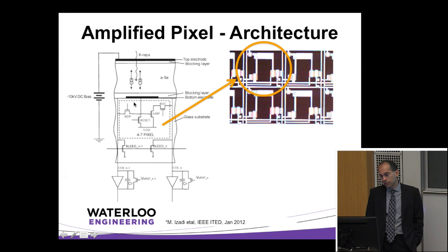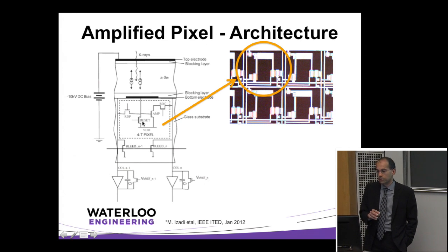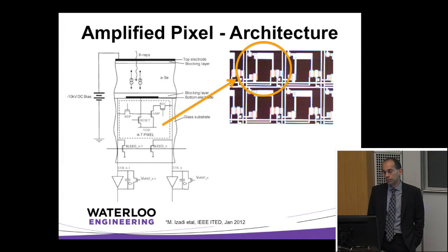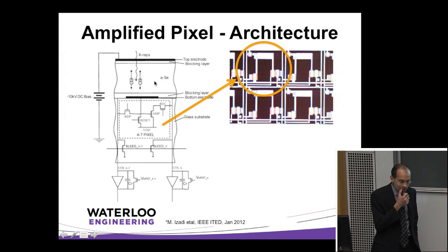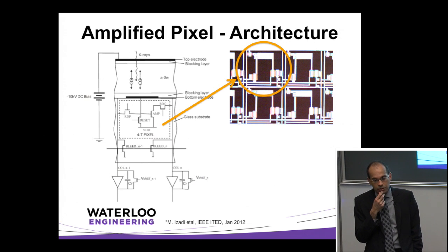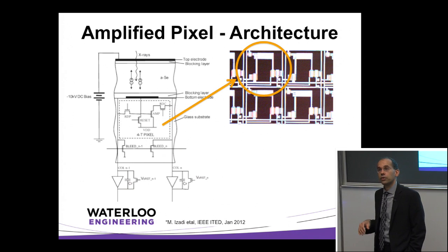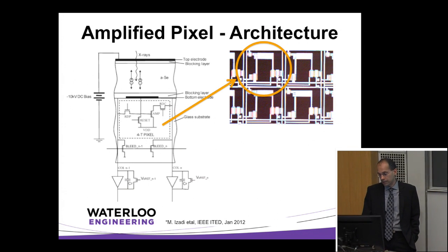So here's another active pixel sensor design. This one's actually a 4-transistor active pixel sensor, not the 3-transistor. We added some additional functionality to increase the dynamic range by putting in the 4th transistor. And we worked with a company based out of Montreal in Canada. They were eventually bought by a US company called Analogic in Boston, and they put the selenium on for us. So we built the transistors, we again did the pixel circuits, they put the selenium on for us.